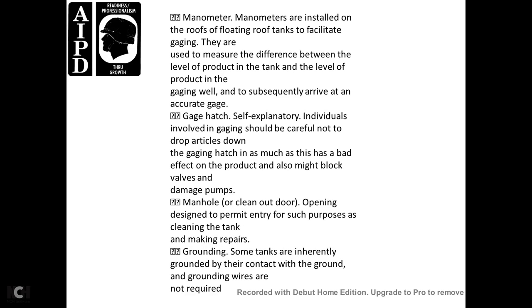Individuals involved with the gauges should be careful not to drop articles down the gauging hatches, as they could have a bad effect on the product, might block the valve, or damage the pump. The manhole, the clean-out door opening, is designed to permit entry for such purposes as cleaning of the tank and the making of repairs.